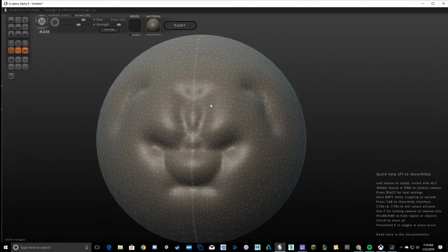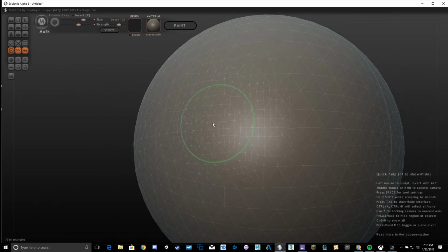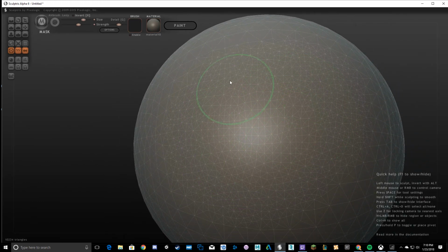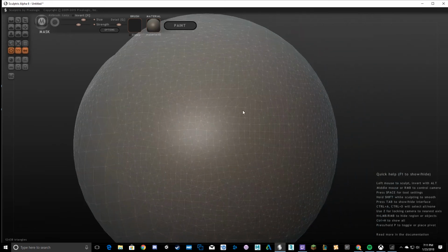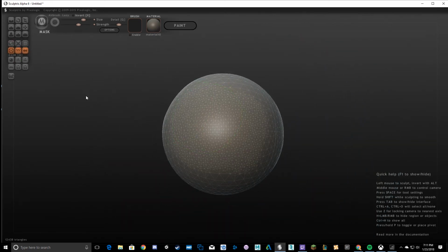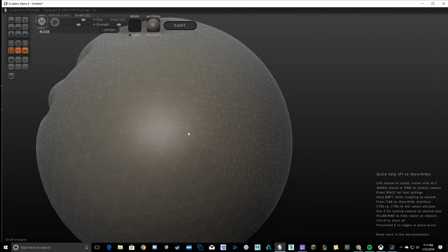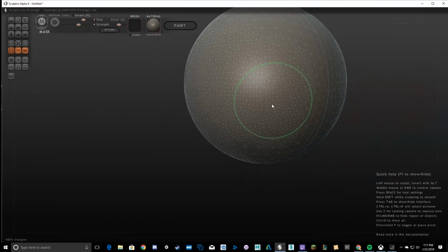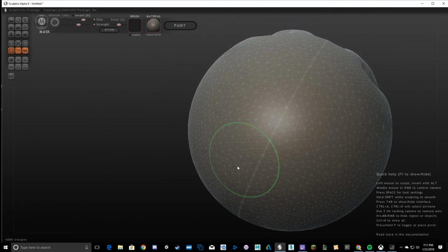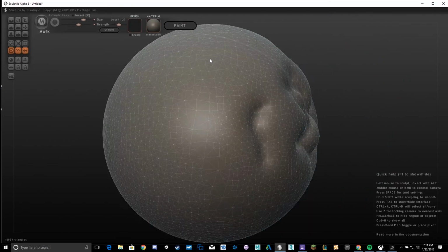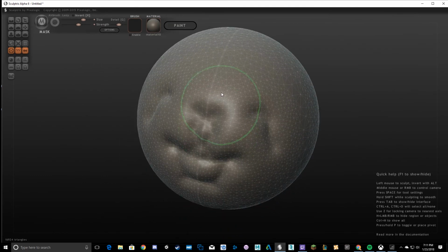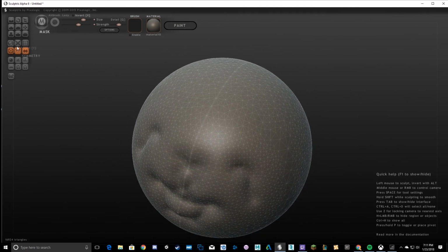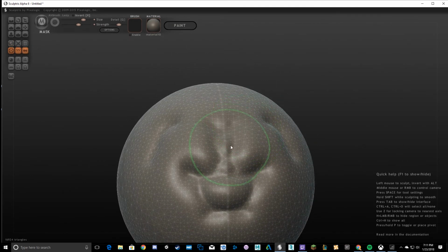What it also does, which I have found useful, is it adds a very high number of polygons to an area. So it's like the opposite of the reduce brush tool in that way. So if you're ever at a point where you want to add a number of polygons, then you use the mask tool. There you go. And that concludes the scene tools portion of the Sculptris tutorial.